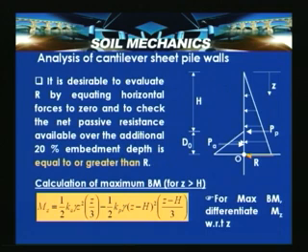And in the further analysis of the cantilever sheet pile walls, it is desirable to evaluate R by equating horizontal forces to 0 and to check that the net passive resistance available over the additional 20% embedded depth is equal to or greater than R.